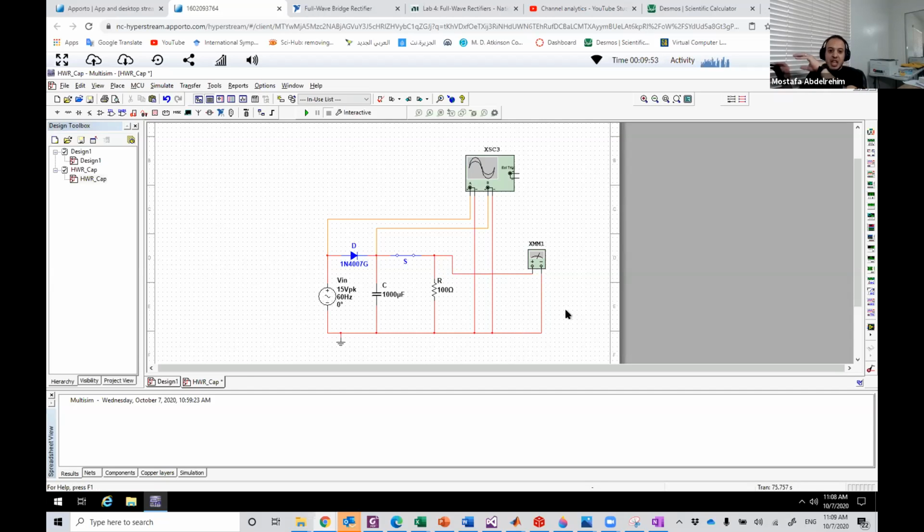One trick, if you have a voltmeter like this or a multimeter that measures the voltage. If you have an AC signal and you want to measure the DC content, you remember, guys, V maximum over pi, this DC stuff, this average value. You can measure it using a multimeter. Just set the multimeter to a voltage, of course, and DC voltage.